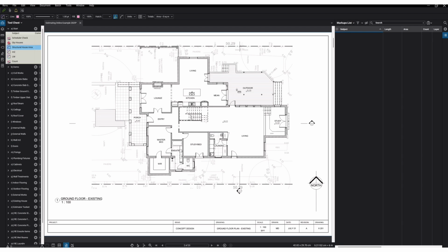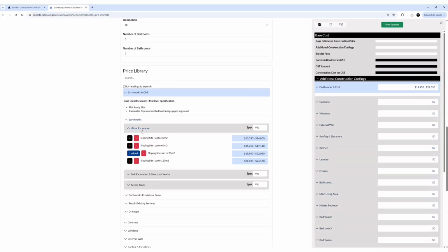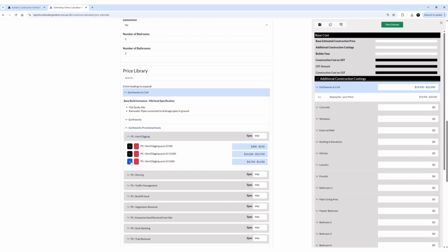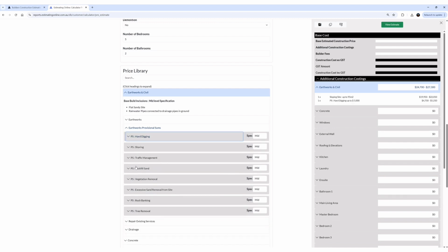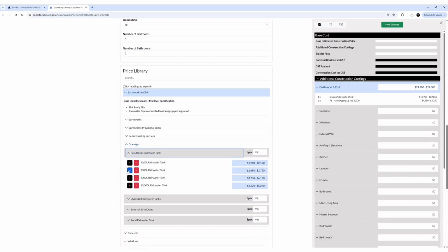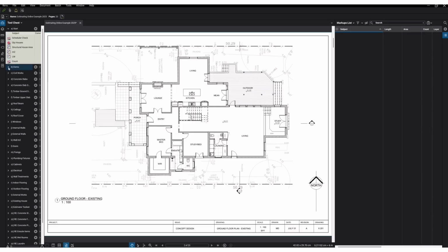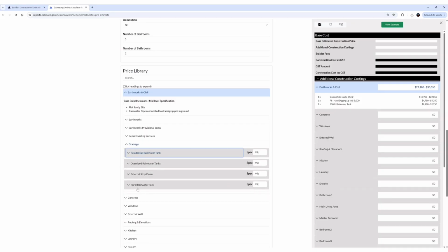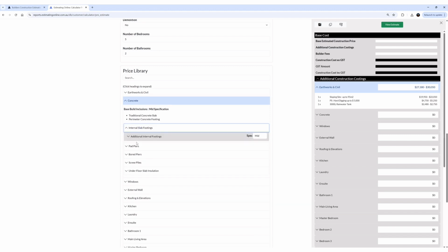I'm not going to be perfect when I do this square meters. As you can see, I've gone past the actual building area. The total square meters on the right is 90 square meters. When I go into my estimate, I'm going to select 95 square meters. I'm also going to add some hard digging costs into the project, and we've got an excessive amount of options to choose from. Due to the size of the roof, we're going to have a 3,000 litre rainwater tank on the project. You can choose not to put it on there. This project didn't have it on the plans, but I made sure that we had an allowance in there.